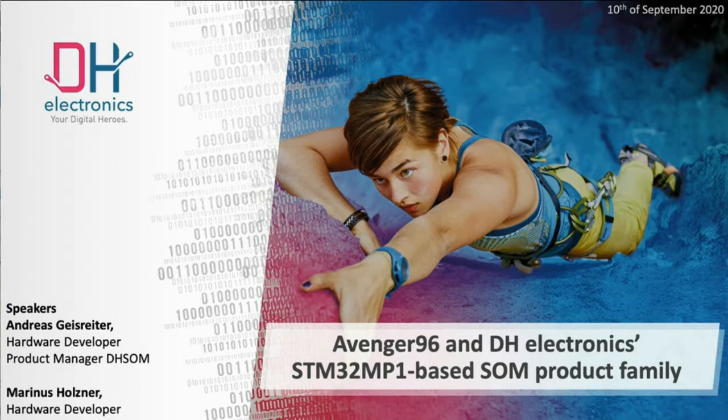Chris? All right, thank you, Marinus. Another question here. Is there a hardware TPM module for secure credentials? This is again Andreas. No, we have no TPM module directly on the module. You can mount it on your own mainboard. But you can also use secure boot mechanisms of the MP1 to secure your system boot. And I think you find more information about this on the ST wiki. Yeah, Chris. All right. Thank you, Andreas.